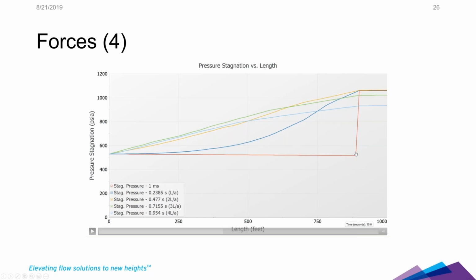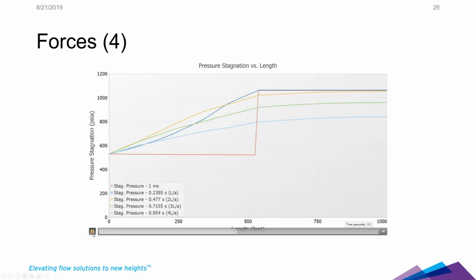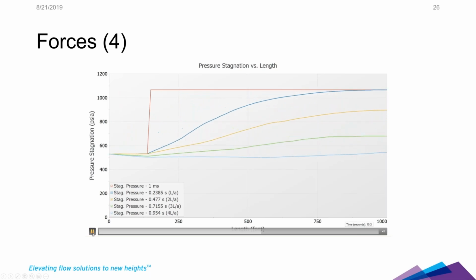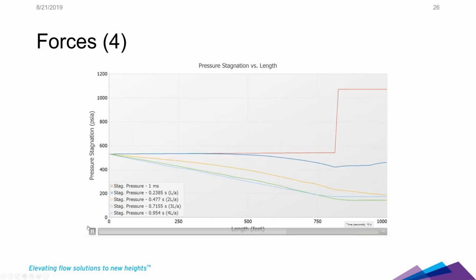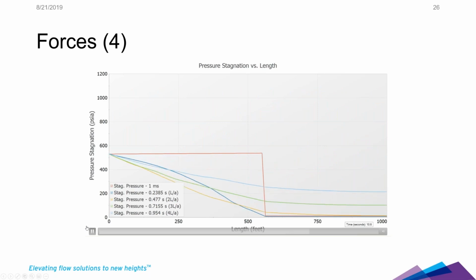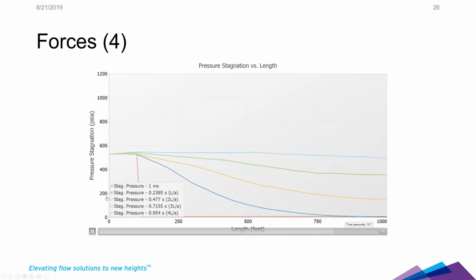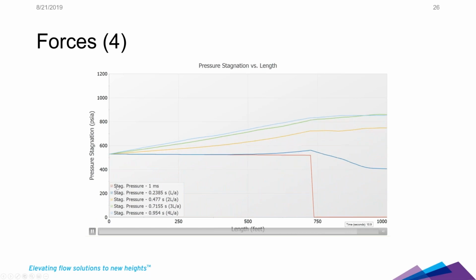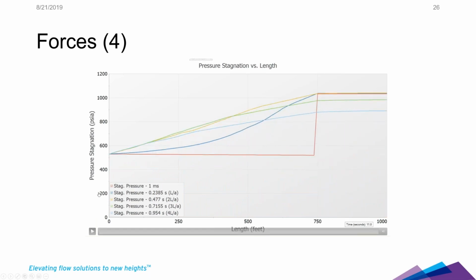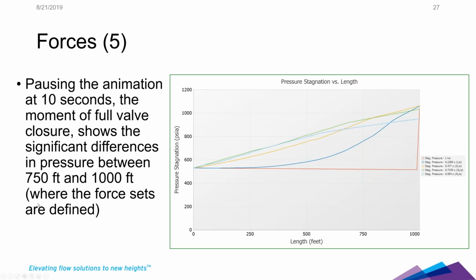You can see this very sharp wave front for this instantaneous valve closure. So you can think about what's the pressure up in the corner compared to right at 750 feet. Okay, so let's watch this go forward a little bit. You can see my faster closure times do have steeper wavefronts. The second steepest wavefront is L over A, but it does not compare to that instantaneous wavefront.